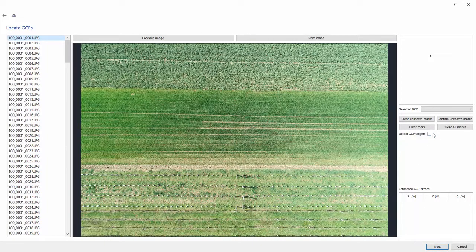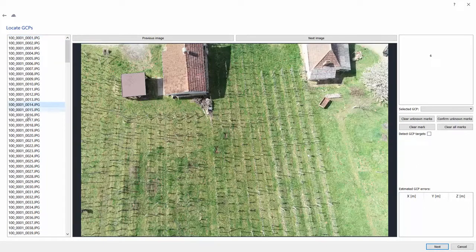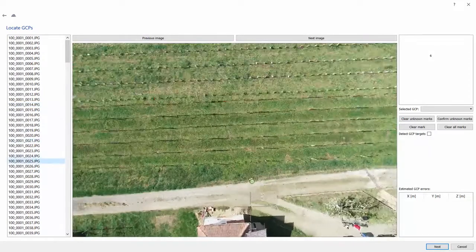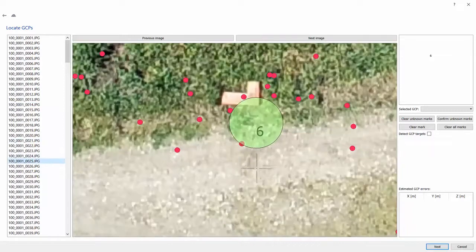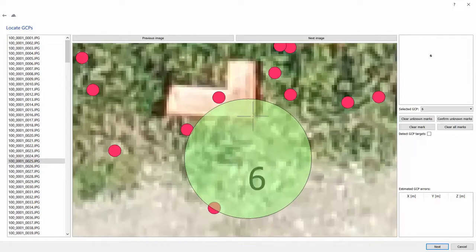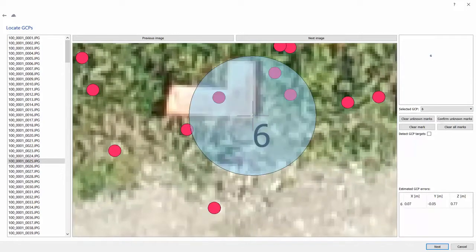This is not a 3D survey target. I just measured one detail point, and I should see immediately the green circle in almost the right position. It was actually this corner of two bricks, which I marked in the field. I will just improve this position now by using the left mouse button on number 6. I could also select it here from the list, and I will accurately show the software. So this is here,